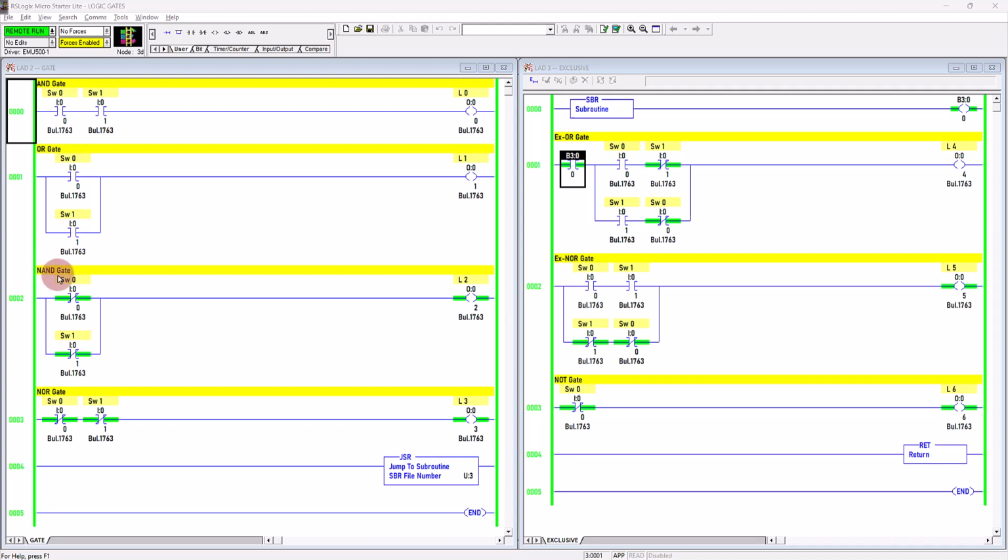As for this NOT AND gate, because it is normally closed, it remains closed for the untriggered condition. And this one will remain normally closed, remain closed. So it's a 1. So 1, 1 here, the virtual power can flow through this rung to energize the virtual output coil. That's why you see it is energized, as you can see from the green color highlight here. Thus, it will cause the physical lamp, which is connected to the digital output terminal point, to light up. That means it will be activated.